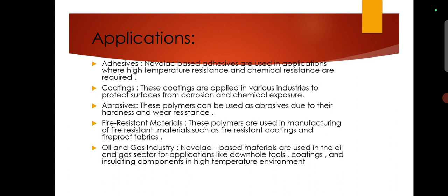Applications of Novolac include adhesives, coatings, abrasives, fire resistant materials, and the oil and gas industry. Novolac based adhesives are used in applications where high temperature resistance and chemical resistance are required. These coatings are applied in various industries to protect surfaces from corrosion and chemical exposure. These polymers can be used as abrasives due to their hardness and wear resistance. These polymers are used in manufacturing of fire resistant materials such as fire resistant coatings and fireproof fabrics. Novolac based materials are used in the oil and gas sector for applications like downhole tools, coatings, and insulating components in high temperature environments.